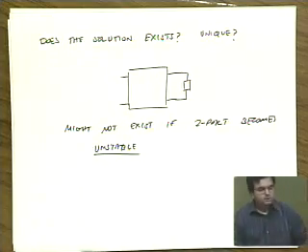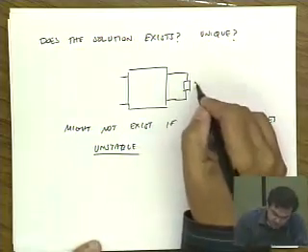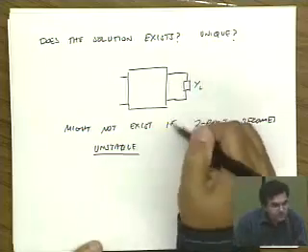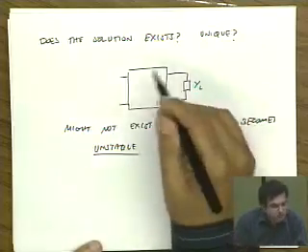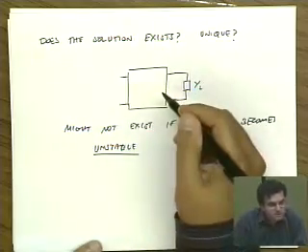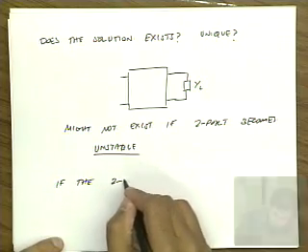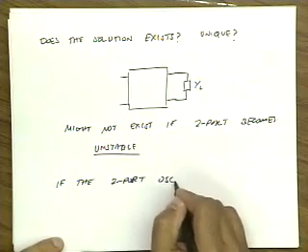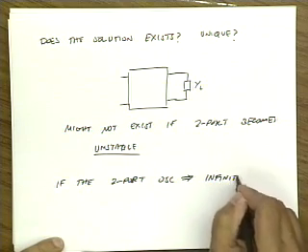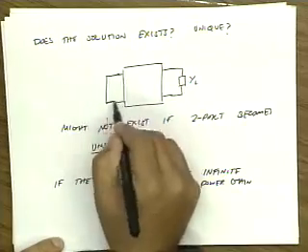We haven't really talked about stability at this point, but just intuitively, if I present a certain YL here that causes the output to oscillate, then clearly this solution for maximizing the power gain, the transducer gain, does not exist. In fact, if the two-port oscillates, that implies infinite power gain. In other words, I might actually just short the input.